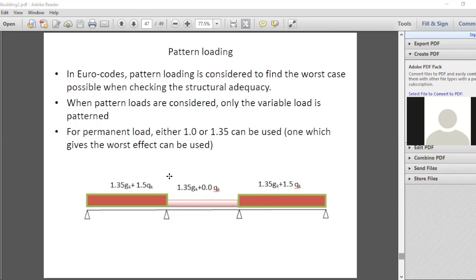And then only you will get the maximum moment here, maximum out of balance moment. And that can be used to calculate the maximum load coming onto the columns. In addition to that, we can also see that with the minimum load here, the maximum bending moment will occur in this particular span and also in this particular span.